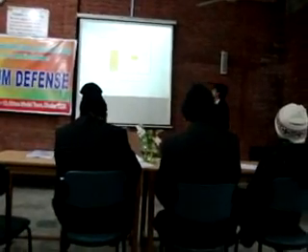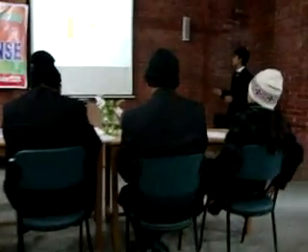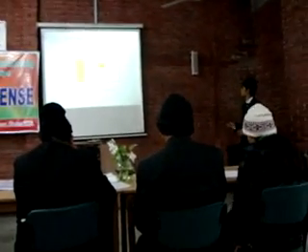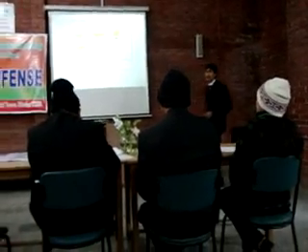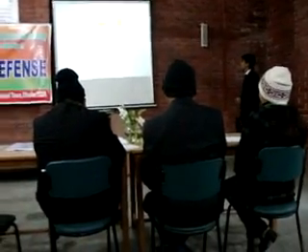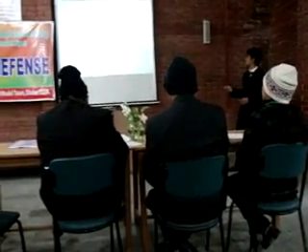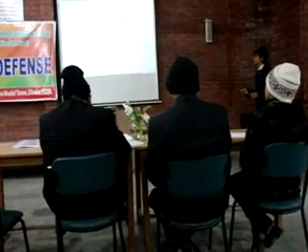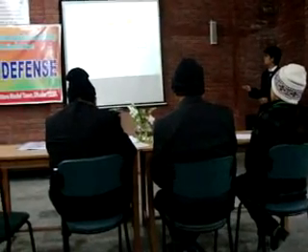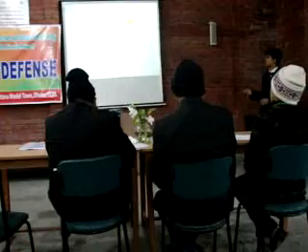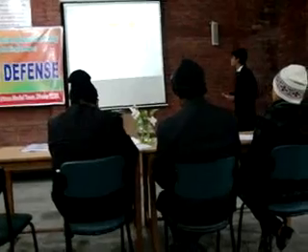Here is the PLC output module connectivity. One is going to the motor starter coil. This coil, if energized, then the motor will start running. And there is a PLC ladder logic program. In the ladder logic program, we have I1, I2, I3, and O1. I is the input devices, and O is the output devices. I1 is the pressure switch, the temperature switch is I2, and the manual input button is I3. So here are 3 inputs and 1 output. This is the motor starter coil.